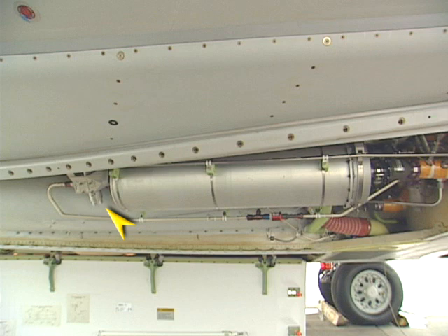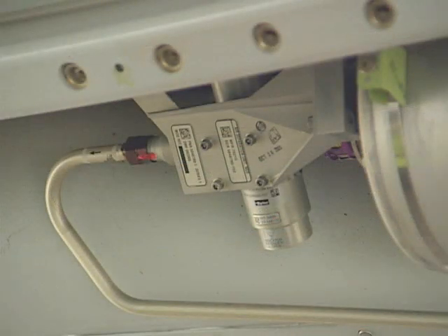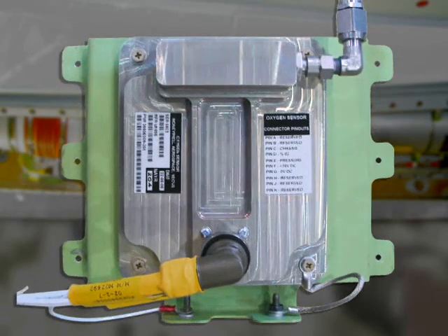Next is the high flow valve. The high flow valve has a delta P sensor that verifies proper operation. You can't see it here, but a line from the back of the high flow valve goes to the oxygen sensor. The oxygen, or O2 sensor, is forward of the ASM assembly, inboard of the ram air duct. The O2 sensor samples the amount of oxygen in the NEA and sends a signal to the NGS controller for monitoring and indication. We'll talk more about that later.